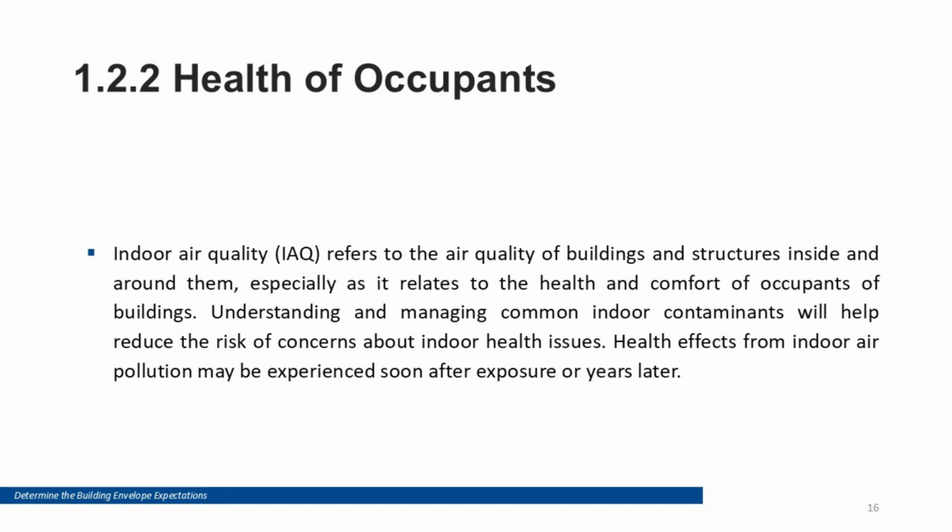Health of occupants. Indoor air quality affects comfort and health. Common issues include irritants, allergens, odours, and moisture-related mould. Building science supports healthier outcomes by controlling moisture, selecting suitable materials, sealing to prevent pollutant pathways, and providing the right level of ventilation without unnecessary energy loss.